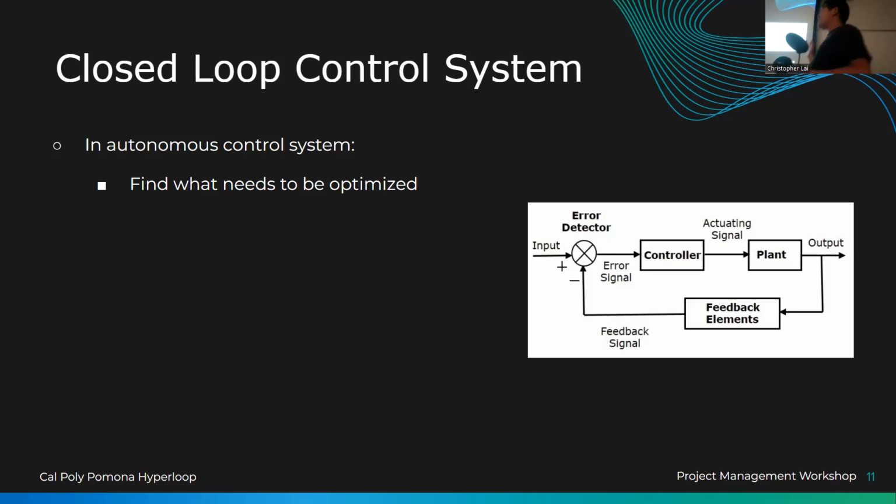So any of these cases would be a case in which I need to find out what's optimized, right? In the event of a self-balancing robot, the optimal point will be the robot balancing itself and not moving. So in this case, it would be the gyroscope returning an angular velocity of 0 on all 3 axes. The drone, in this case, would be the same thing. We want it to hover. That's the optimal point. So any error that gets generated from this drone will be based on the inertial measurement unit. It'll be the angular velocity not being 0.